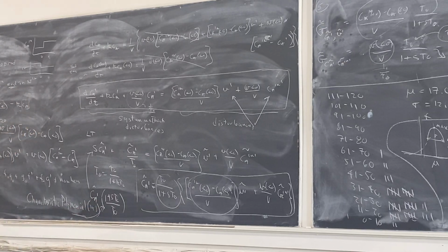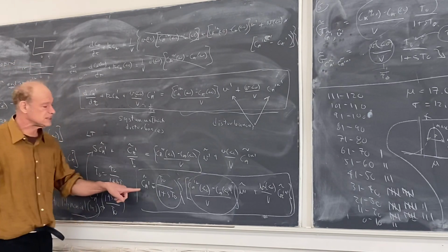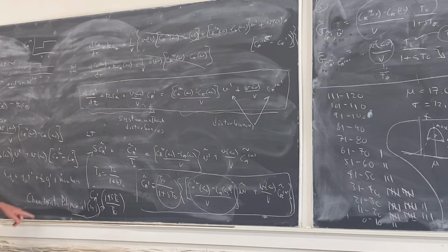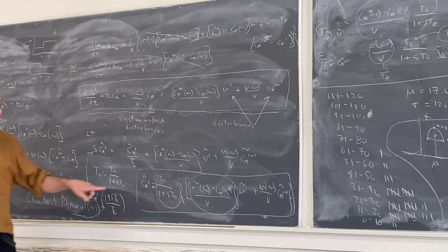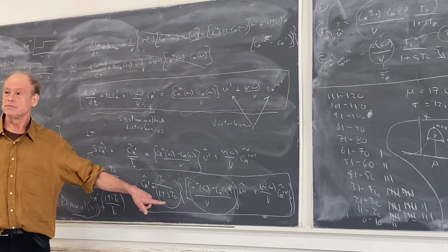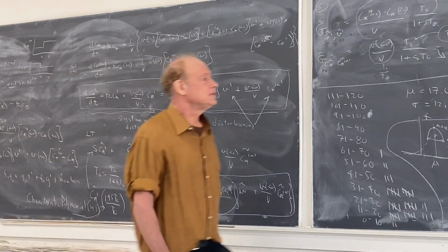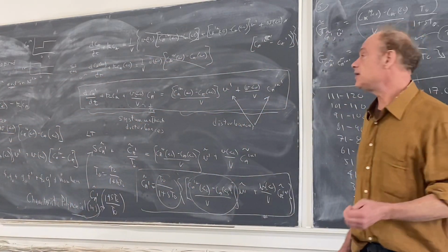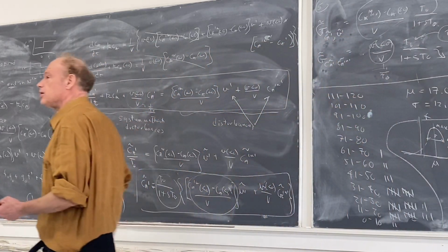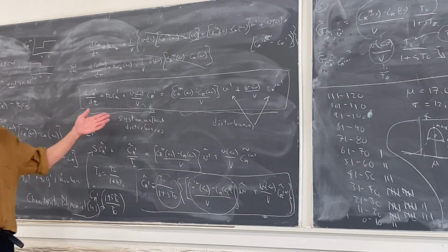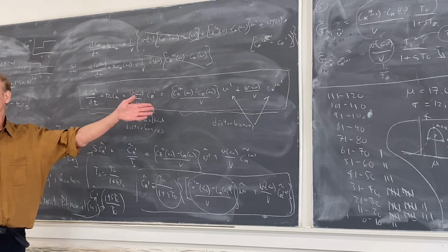It's called the characteristic polynomial because it's characteristic of the system and not of the disturbance. For any disturbance, I always have the same characteristic polynomial. And notice that when I write out Ca prime tilde, it's the characteristic polynomial that goes in the denominator. So the left side of the equation is the system, the right side the disturbances.